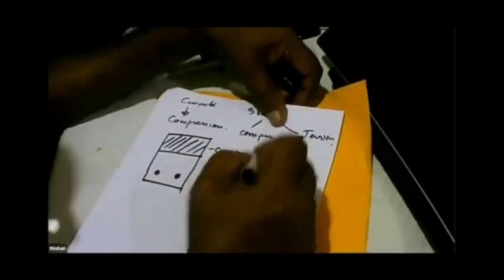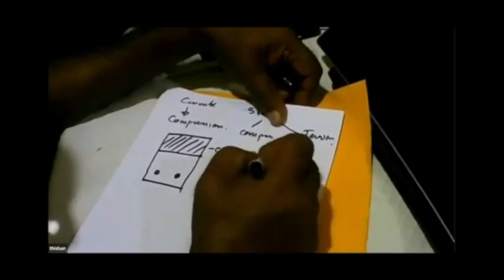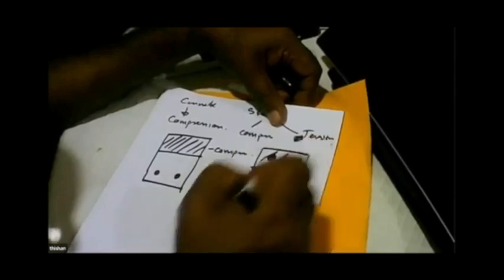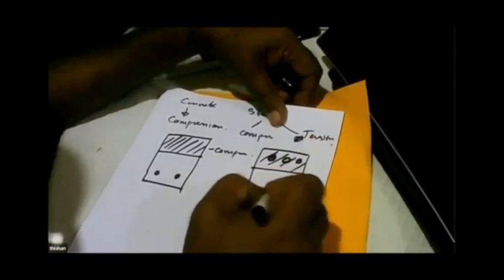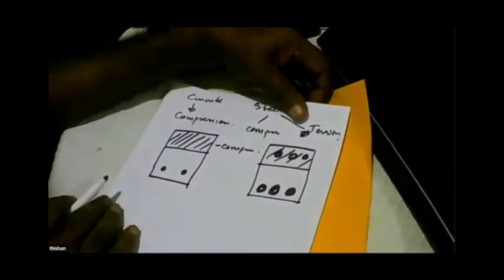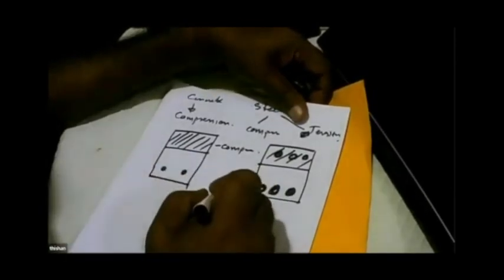To get a situation where you have to doubly reinforce the section like this, what is the meaning? Meaning is wasteful design.